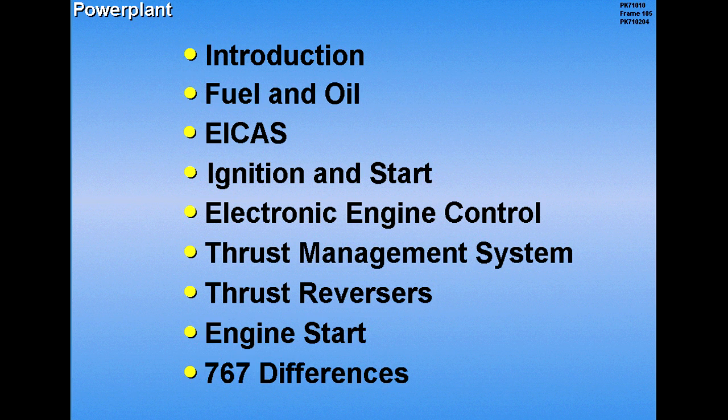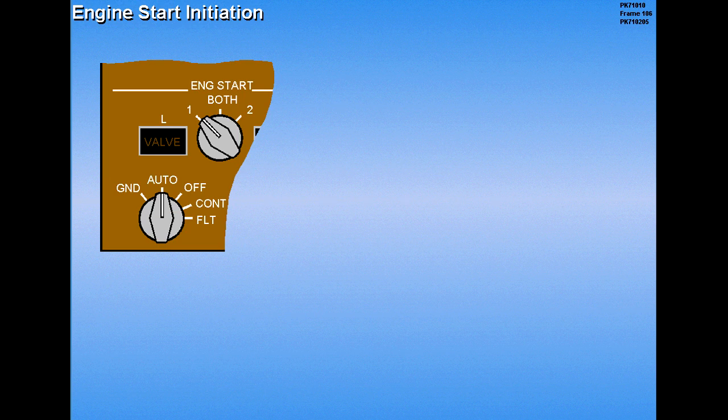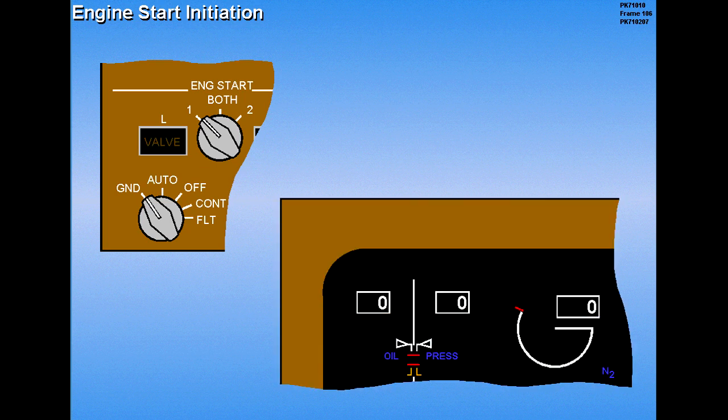Now let's look at a normal engine start sequence. Engine start is initiated by pushing in and rotating the engine start selector to ground. The engine start valve light illuminates momentarily as the start valve opens. N2 and oil pressure should start to increase.